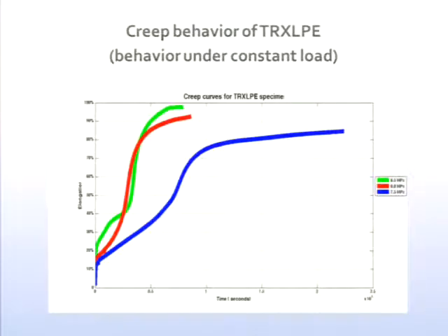These are creep curves. So this is the business of applying a constant stress to the sample. This is not fatigue. This is a constant load applied to the sample. And these loads are shown over here on the right-hand side. So at 7.5 megapascals, the stuff undergoes some sort of elastic deformation to start with, and then it slowly gets longer and longer, and suddenly it starts to fail at that point there. And of course, if you go to higher stresses, then the failure occurs much earlier. And this is time in seconds. I think that's 10 to the 6, 10 to the 4 down there.